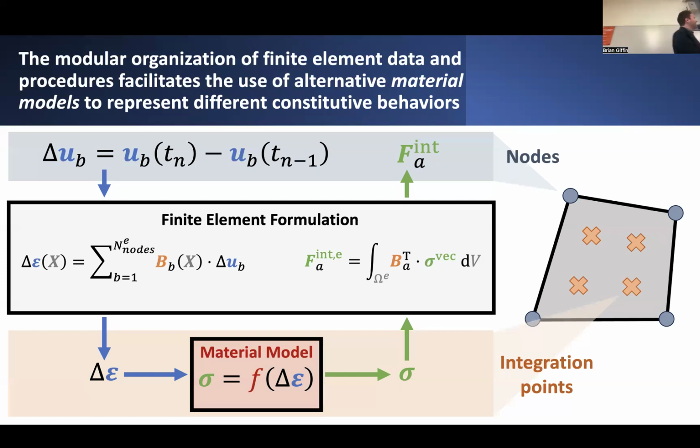Then once you have that, you can use that new stress in the material to integrate the resulting forces that act at each one of the nodes of a given element. You can assemble those forces into whatever global system of equations you're trying to solve. You can use that to iterate and solve for equilibrium, assuming that this relationship might involve some nonlinear relationship between the strain increment and the corresponding stress in the material.